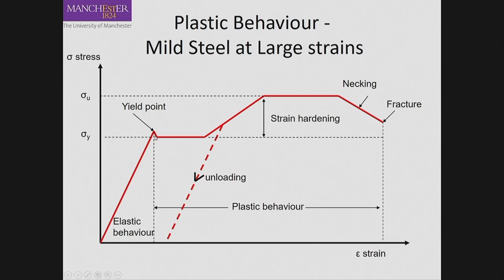But if you go beyond this yield, that doesn't happen. If you go beyond that point and release the load, you'll come back to the zero stress position in this case, but it may not have come back to the same shape.